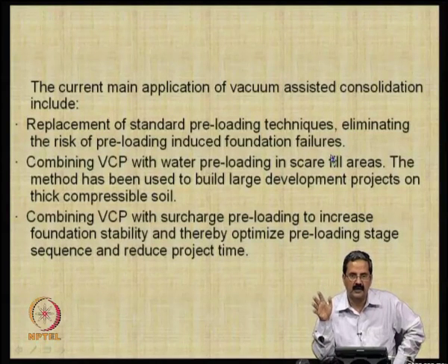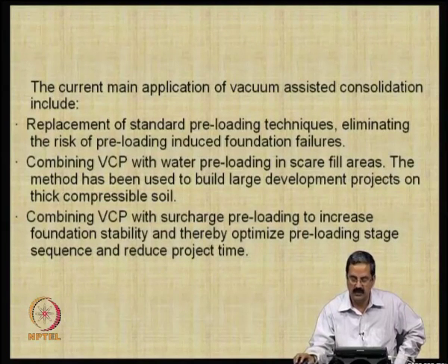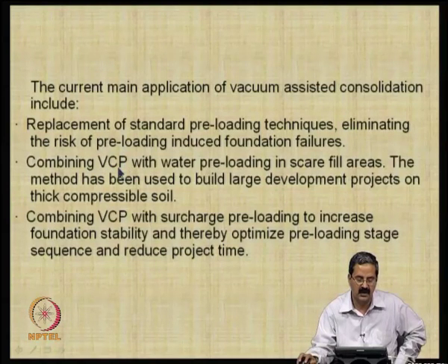You try to stack all the preload in one place, but it could lead to failure. So, what should be done? You try to combine vacuum consolidation preloading with conventional preloading, so you can have both of them, in areas where there is a scarcity of fill.